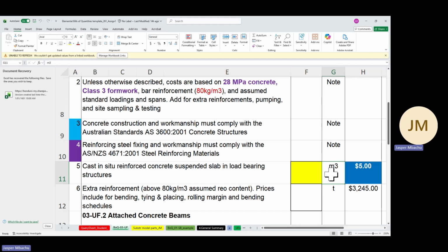So what we have learned to do is to identify those floors and use duplicate and rename type to tag them as upper floor. So when we are pulling out floor quantities in a Revit schedule, we will be able to identify which of those floors we are interested in for the upper floors. So we've used the type, when we say UF, then 03 level 1, upper floor isolated slab, we know that those are the slabs that we need to aggregate the quantities for and provide them here, not manually.